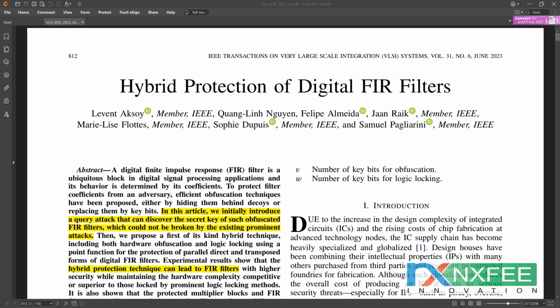To reduce the hardware complexity, this paper proposed approaches for the arithmetic operations with a XOR-MUX full adder design to reduce the number of logic gates in the FIR filter architectures. It is also shown that the product multiplier logic blocks and FIR filters are resilient to existing attacks. The results on different forms and realizations of the FIR filter show that the parallel direct form FIR filters have promising potential for secret design. This work was developed in Verilog HDL and synthesized in a Xilinx Virtex-5 FPGA.